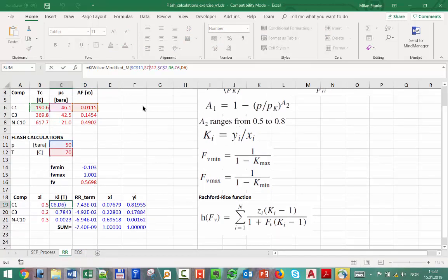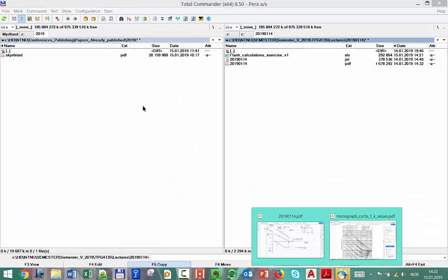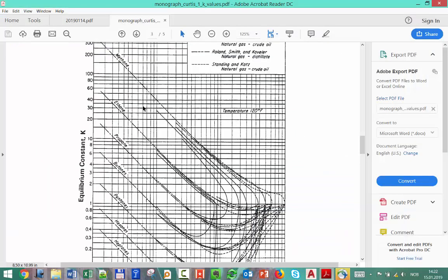Now, on the nonlinear part, when we are starting to approach this convergence pressure, remember, it's fictitious, it doesn't exist. Only when you are at the critical temperature do all of them join in the same point. For all other temperatures, it's going to stop someplace at the bubble point pressure or at the dew point pressure. It doesn't exist.